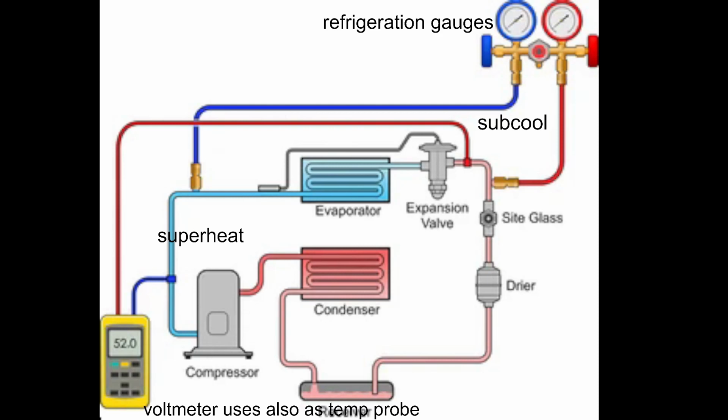All you need to do is make sure that you get a subcool reading and make sure that it's within the range. Some of the units, like Carrier, will put a marking on their nomenclature. Their nomenclature is their identification plate, and it'll have a subcool reading on there, and you just got to get close to that one. But I will go through a mathematical equation with you on how to do a subcool without using a sliding chart.